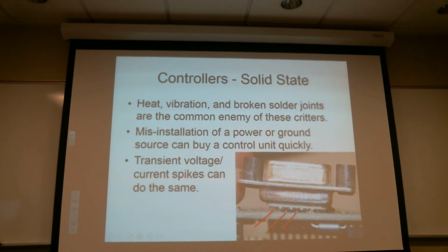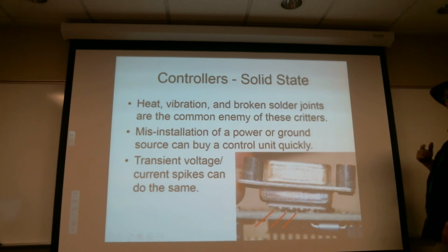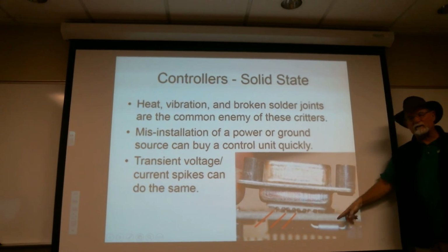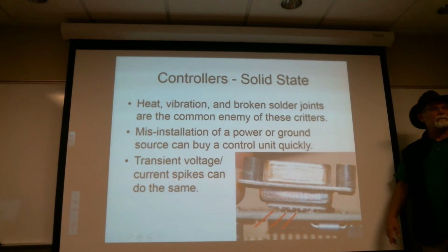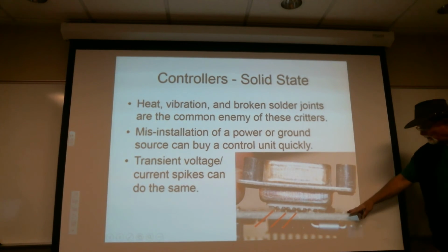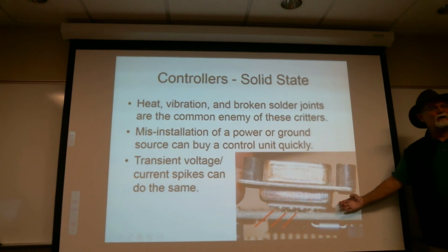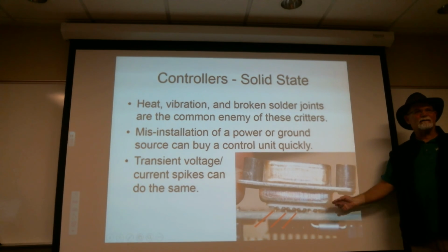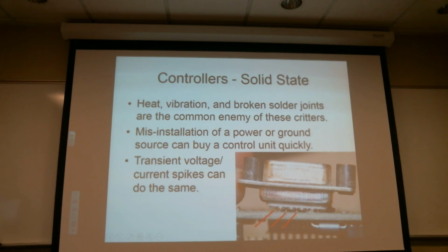Now, the irony of all of this is the proper chassis mount RS-232 has two pins that come down and connect to the board, and it's soldered in place. There are two big pins. The board, you can't see it, has two big holes with solder pads for that type of connector to be installed in place. This isn't a chassis mount connector. My guess is the company isn't actually building those boards. They've subcontracted that out. And somewhere along the line, somebody made a change to those RS-232 connectors.